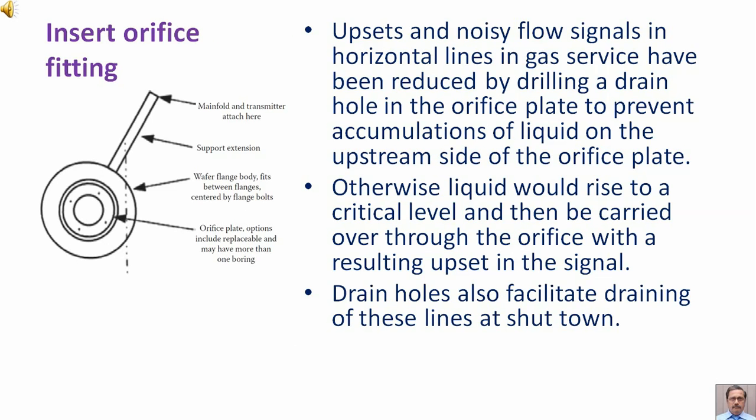Upsets and noisy flow signals in horizontal lines in gas service have been reduced by drilling a drain hole in the orifice plate to prevent accumulations of liquid on the upstream side of the orifice plate.